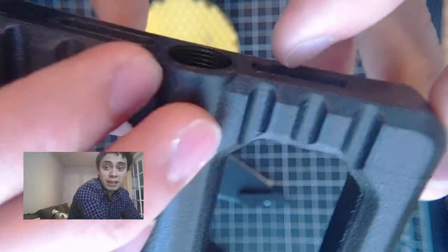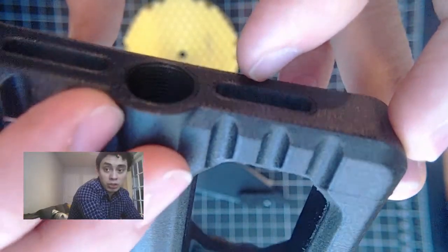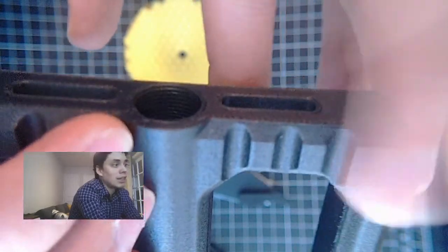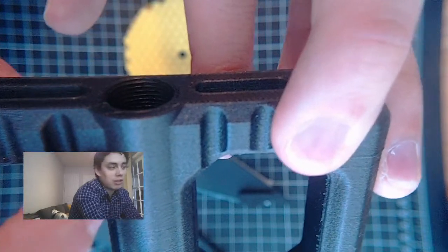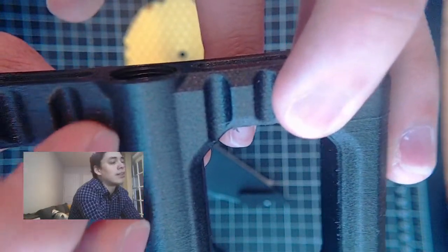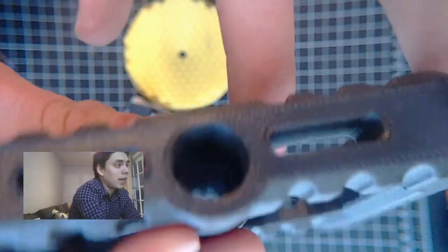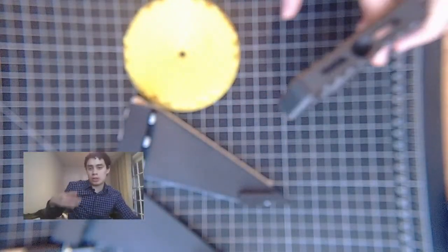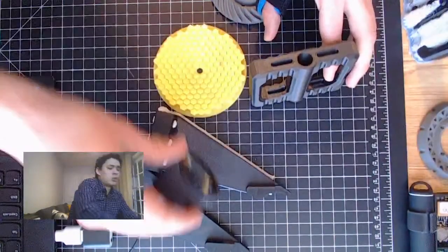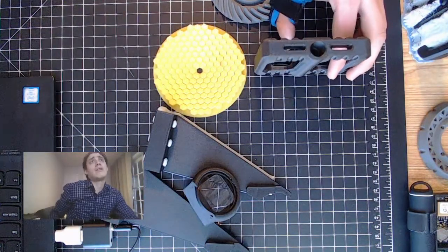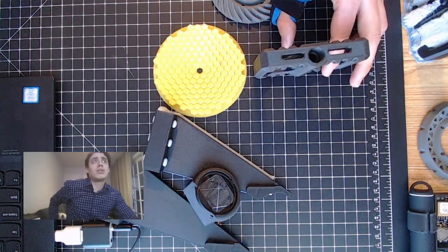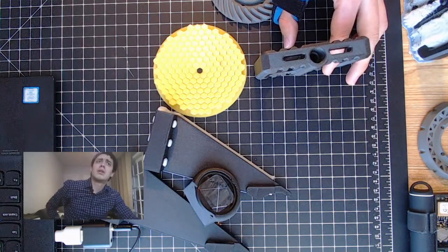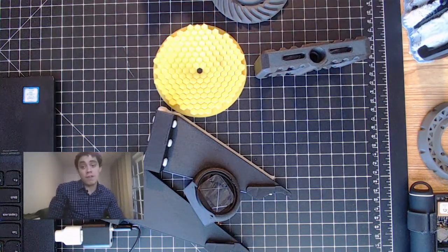So definitely in part due to the orientation of the part, right? I have a lot of layers describing that particular thread. In this one, it's close to 1 centimeter section, so a little bit less than half an inch. I probably have a good 150 layers to describe that. You can do the math. I was using 200 microns for steps. So if I have 100 millimeters, so that's 1,000. Does that make sense? No, 500. 500 layers to describe that.